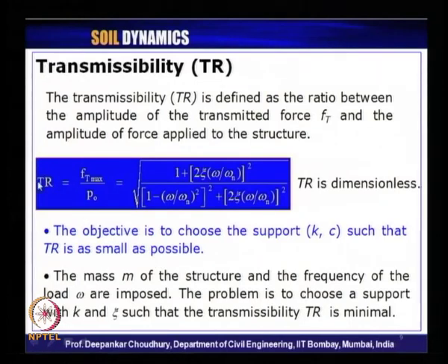Because a small transmissibility ratio means, for this given force to the system, on which you hardly have any control as a civil engineer, since it is provided by the machine manufacturer or supplier, what you can do is design a system in such a way that the force transmitted to the base of the foundation should be minimum, right.